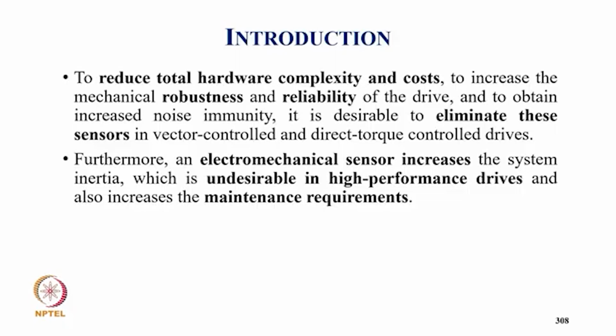It is desirable to eliminate these sensors in vector control and direct torque control drives. Further, an electromechanical sensor increases the system inertia, which is undesirable in high performance drives, and also increases the maintenance requirement.